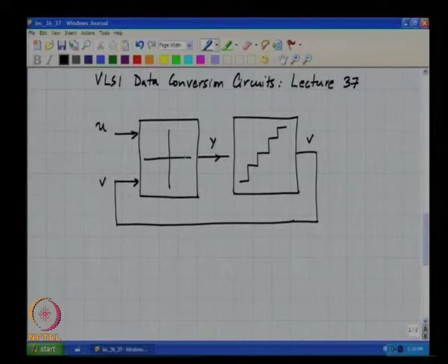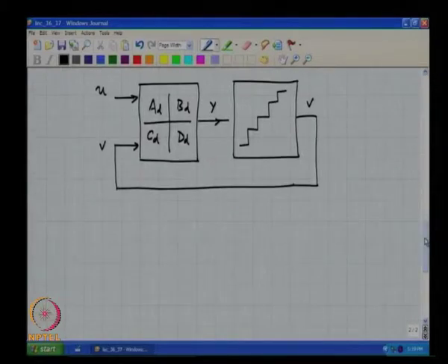and can therefore be represented by the state equations, the difference equations which can be recast in state space form, alright, and the state matrices are given by A D, B D, C D and D sub D, right, and the state formulation is that the set of states x, please note that x is a column vector at instant n plus 1 is linearly related to the set of states at instant n plus B D times the inputs to this linear system, which are u and v.